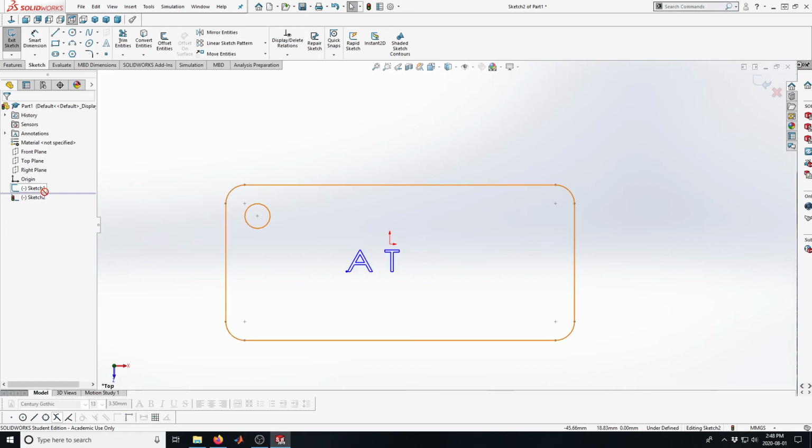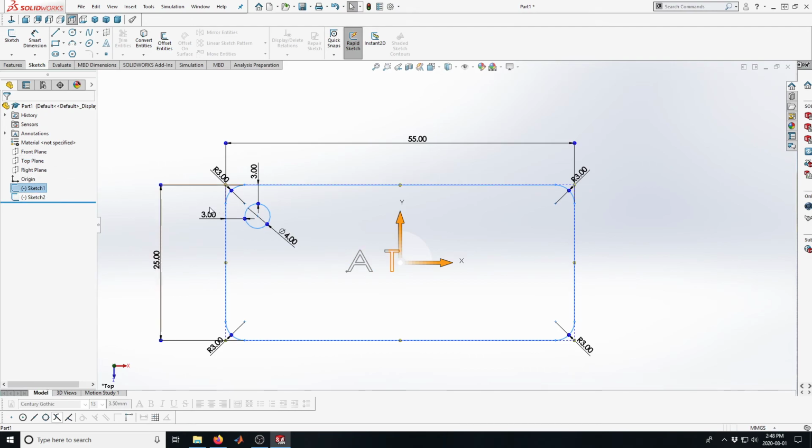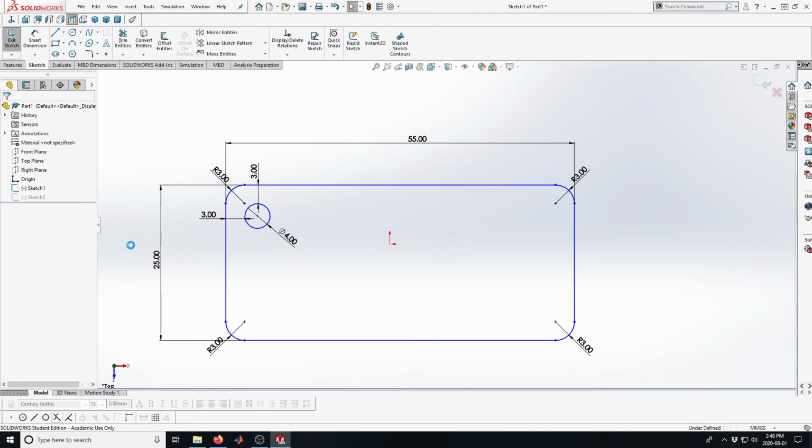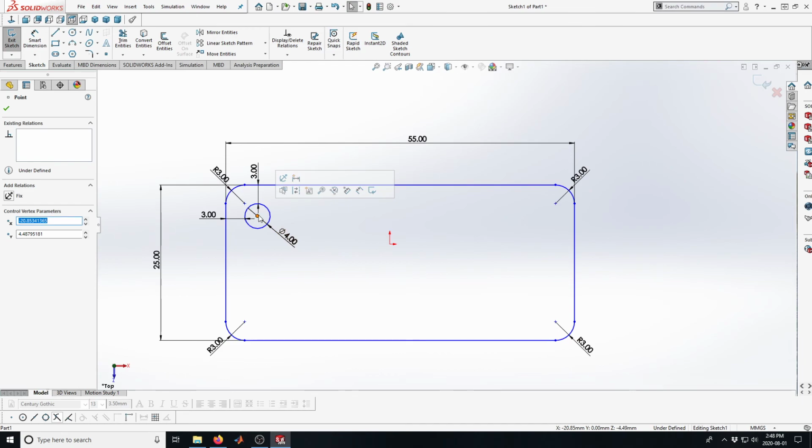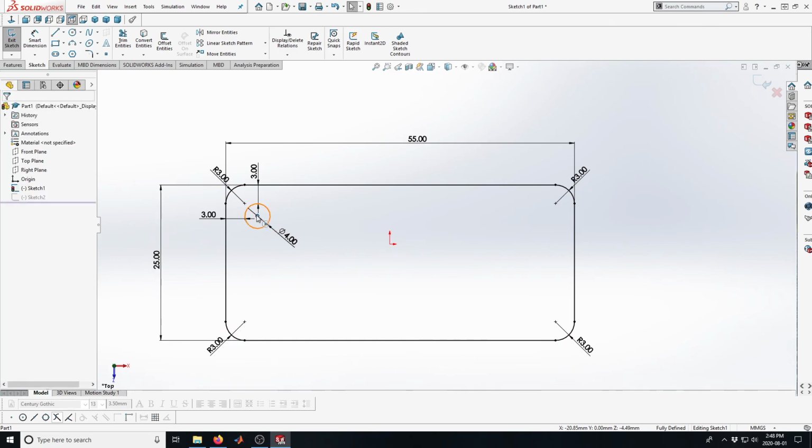One other thing, notice that in the previous video I showed about whether or not the parts were fully defined, and notice with these sketches, after the sketch there's a little negative sign in brackets. In addition to showing you that the sketch elements are in blue, that also indicates that the whole sketch itself is underdefined. So I can edit that sketch, and I'm going to pick this, and I'm going to fix that point. Bam. So I just fixed the center of that.